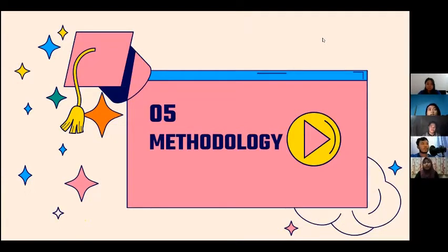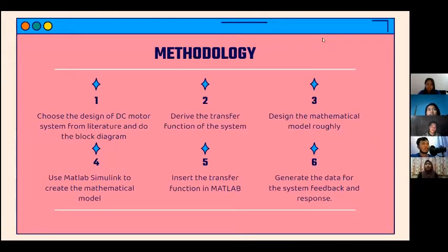And as for the methodology, I will present. First, we choose the design of the DC motor system from the literature review and roughly draw the block diagram. Then we derive the transfer function of the system and design the mathematical model by referring to the literature review. Then, using MATLAB Simulink, we are able to create the mathematical model. We also insert the transfer function that we designed in MATLAB, and we are able to generate the data from the system feedback and the response.